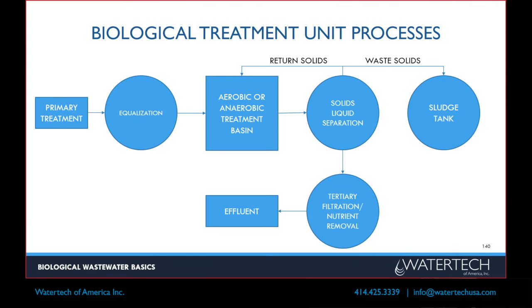And then, as we'll talk about, the outcome of biological treatment is the more waste you treat, actually the more bacteria it reproduces as you treat waste. So the more waste you treat, the more leftover you get, and you have to waste some of those solids from your biological system. Otherwise, you end up with a poor population of biology that will cause all sorts of other issues.